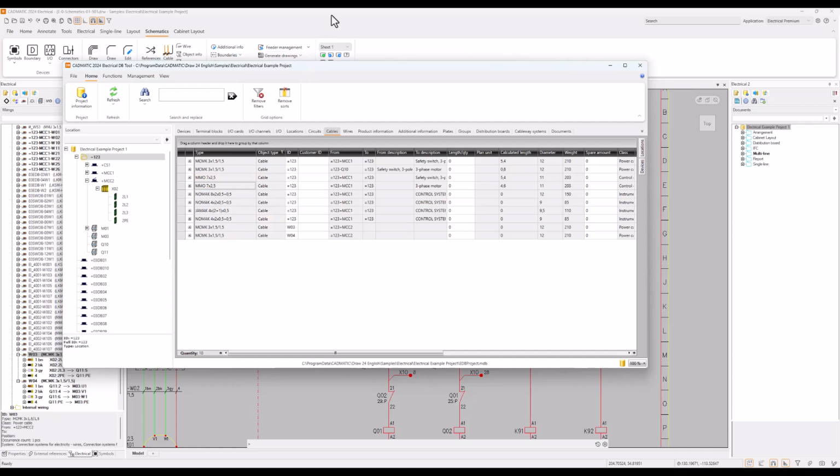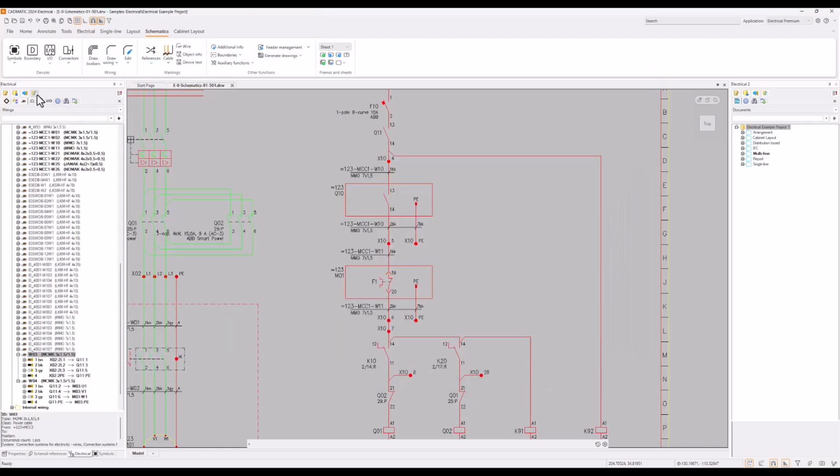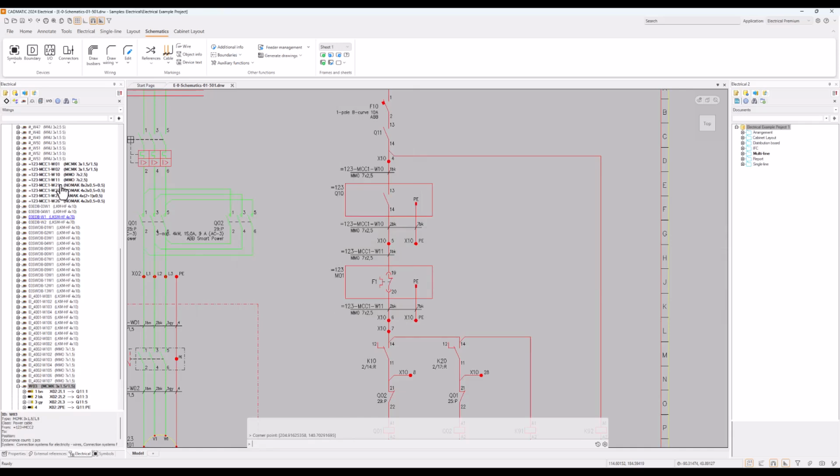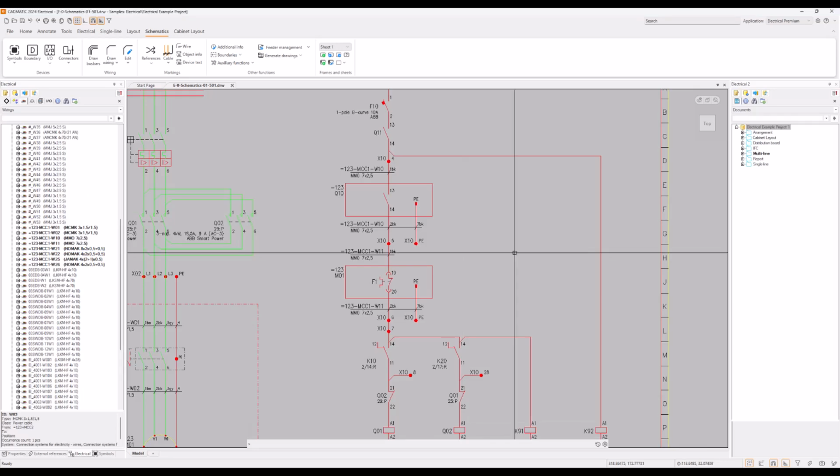And once we go to the drawing, now no editing is on anymore, so we can synchronize changes from database to drawing, and there you can see the MMO changed there, there, and there. And there was some mass editing done for the cable types.